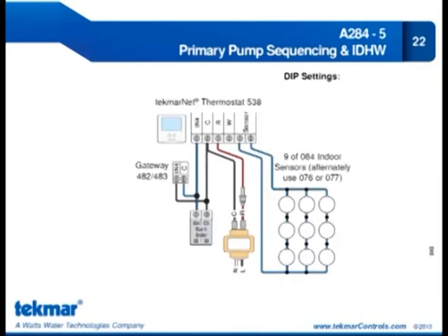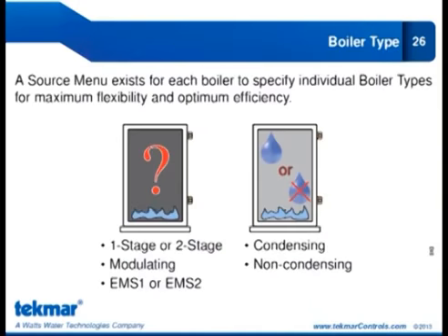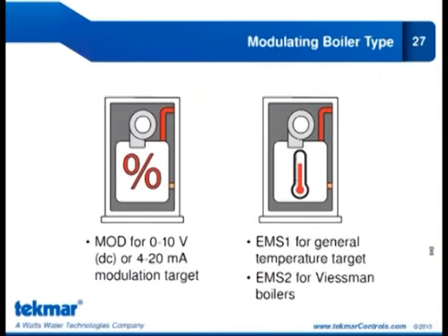For example, on the Vitodens 100, 200, we can tie in. Typically you can only use a Tecmar 400 series product with the Tecmar stager function, so it outputs a 0 to 10 volt DC signal, mapped to the Viessmann temperature range. But we've never had the capability to control multiple units.